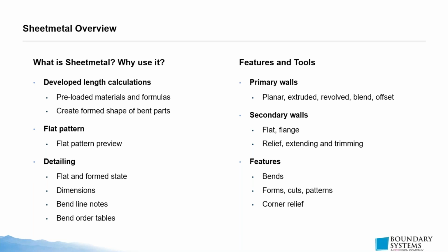It can be functional in order to make your material fit together better. Or I suppose it can be cosmetic a little bit as well. These are completely customizable. There are several pre-loaded types of corner reliefs that you have the option of choosing. And additionally, you can create your own, modify the dimensions of each of these types of relief as well.